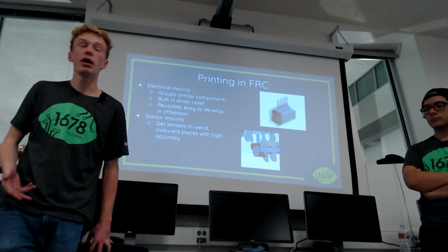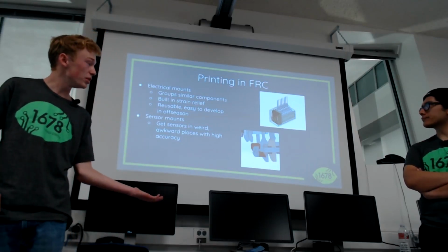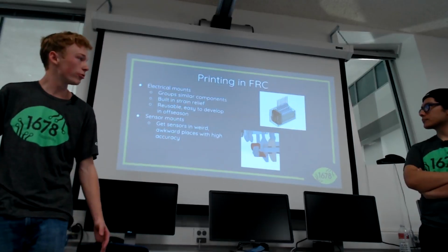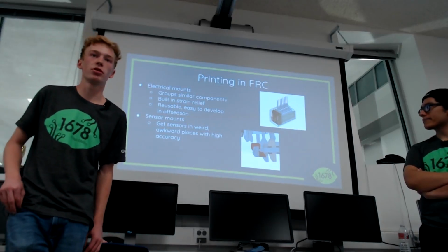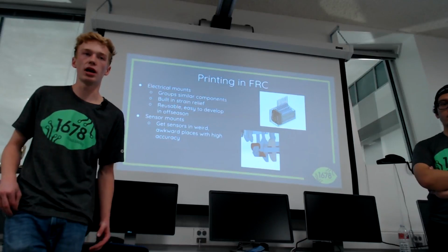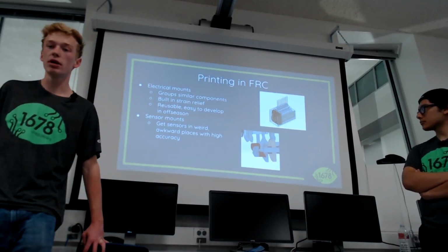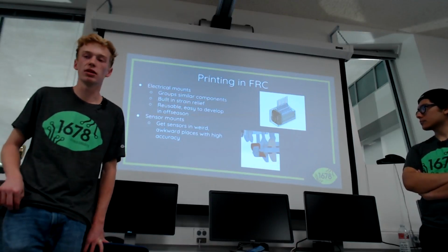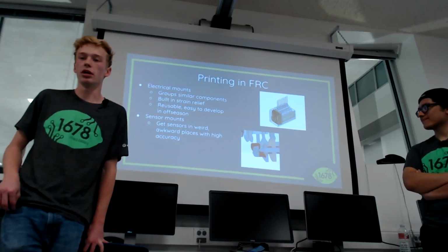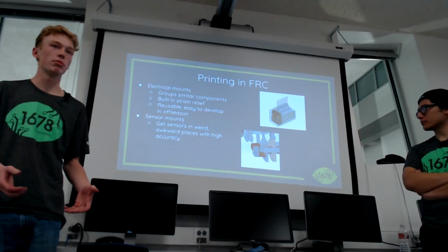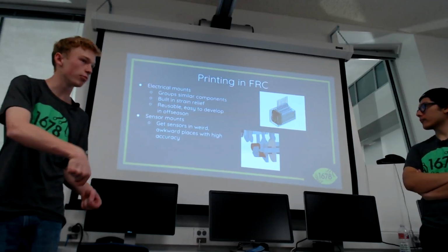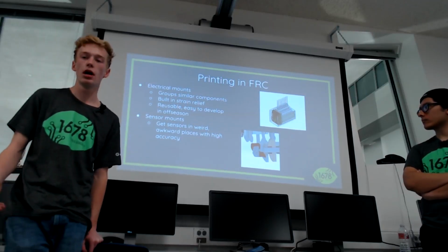You can free up some belly pan area. By taking that PCM and moving it vertically, we free up a little bit of space, which reduces some constraints on other areas of design. You can have more mechanisms encroaching on that space. And lastly, it makes the electrical team's life a little bit easier because they can have these modules pre-assembled, and they can have wire strain relief, zip tie paths, and all these fancy features,